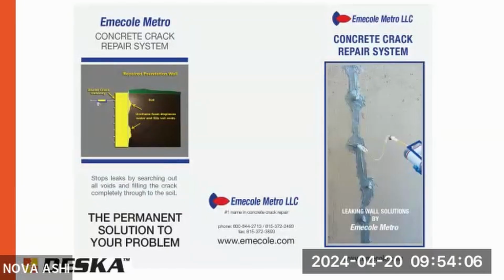So epoxy injection. If you have cracks in foundation walls, you don't want that water getting in the wall and touching that steel reinforcement, for the same reasons as the lintels and the reinforcement. And so injecting it, not just caulking the surface, but actually injecting it. Typically we recommend epoxy because it's a structural repair as well. But depending on the size of the crack, you can also use polyurethane, though there are expensive polyurethanes. It really depends on what you're trying to achieve.